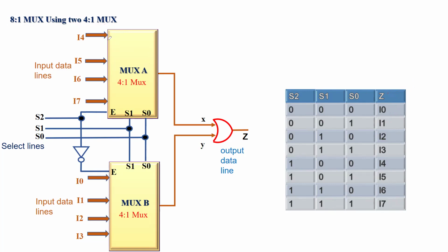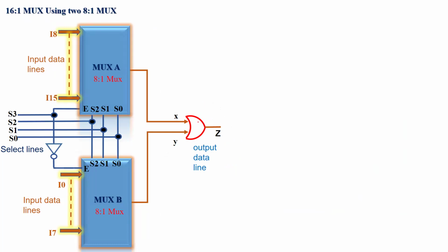Remember, you can compare this module with our previous modules where we were using multiple multiplexers, but here we are using a logical OR gate and reducing the number of MUX that will be used. Here in this exercise, we have used only 2 MUX. It is also possible to use 3 MUX, but now we replaced 1 MUX with the OR gate. So think about that. Having said that, we can move to the next one.